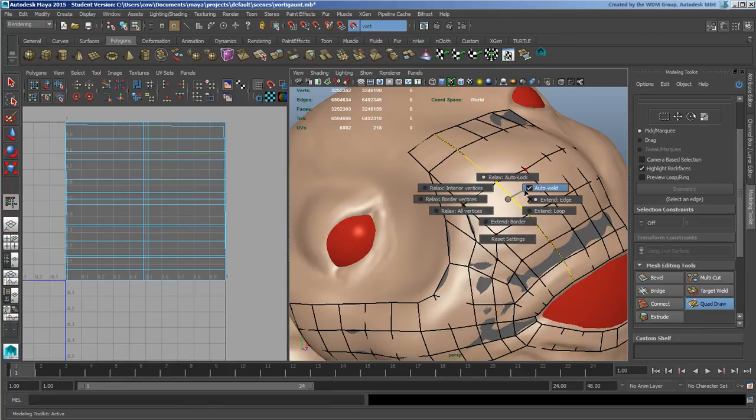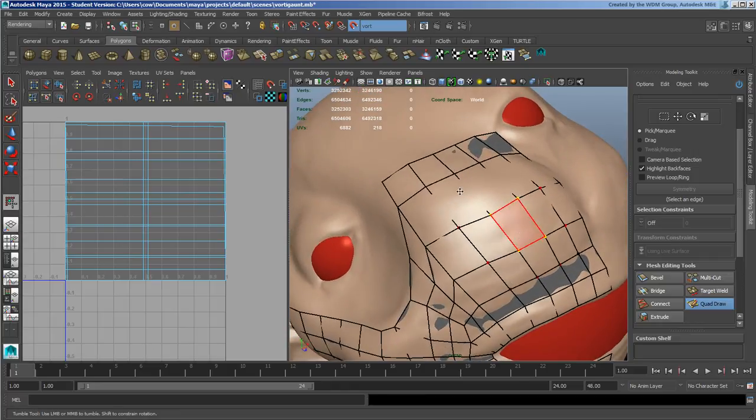And then we have the option to turn off auto weld if you don't want to use that. And then we have some automated features for some of these things, which I like the way they exist right now, so I don't actually change these. Right now it's set to go ahead and extend an edge. That's when I go ahead and use Tab and drag out.